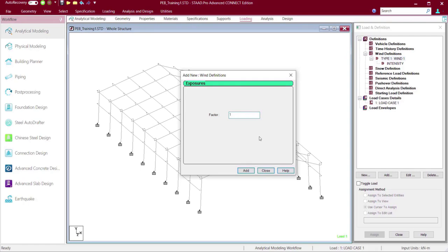Similarly, if you want to define any other type for some orthogonal action, for example, the wind hitting from the other orthogonal direction, and assuming that this face is not 100% exposed to the wind load, so basically its effective area is much reduced. In that case, you can't assume 100% effective area. You need to reduce the exposed area. So just go ahead in the factor box where you define some reduced value.